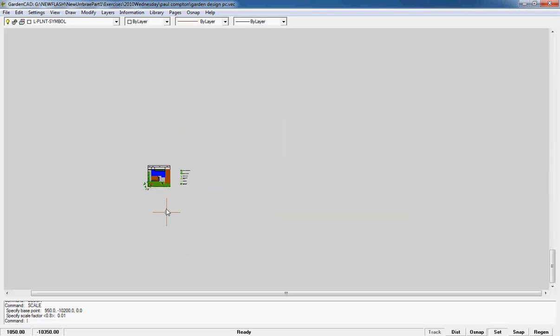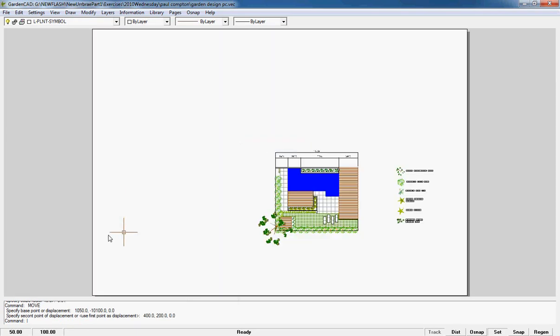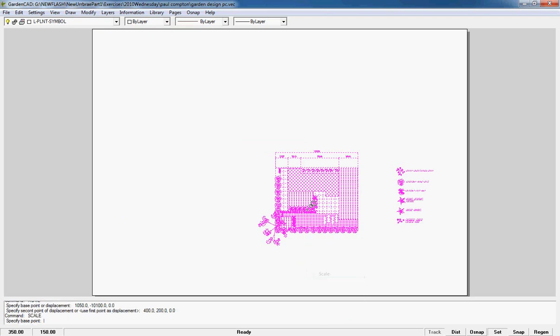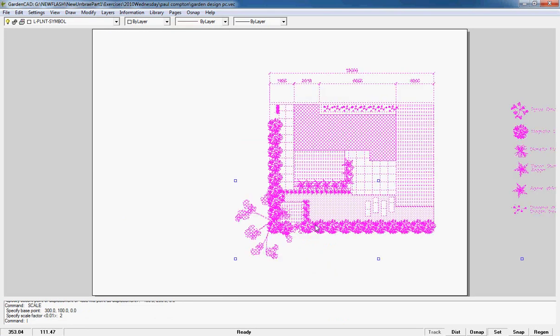Way down here is our scaled drawing information. Now you'll see the value of having it as a single block. We can move it and drop it and put it directly onto the sheet. Then a quick zoom extents will show us how we're going. Now clearly 1 to 100 is too small, so we can very easily scale that up. So scale it there and double it. So we're making it 1 to 50, and then we should be able to drag it across, move it across.